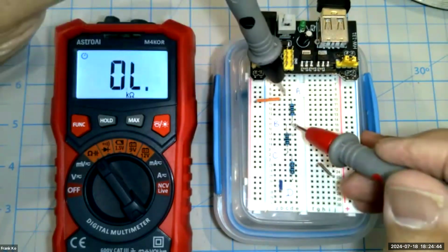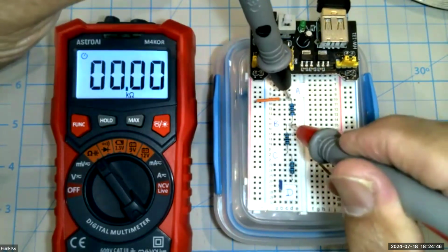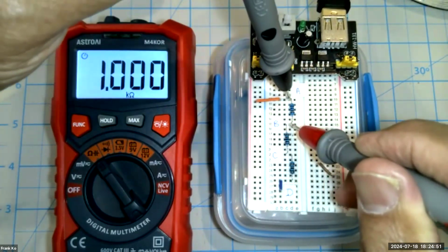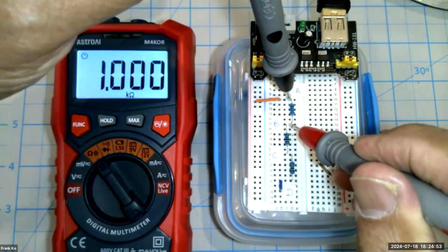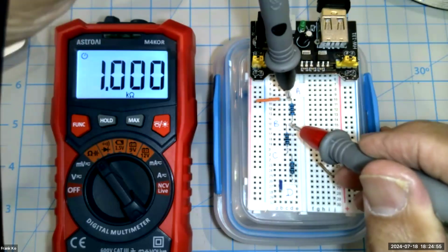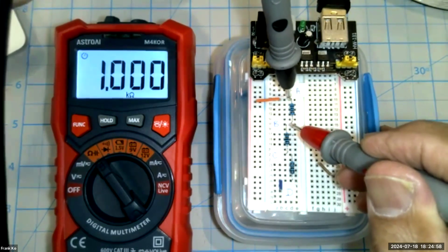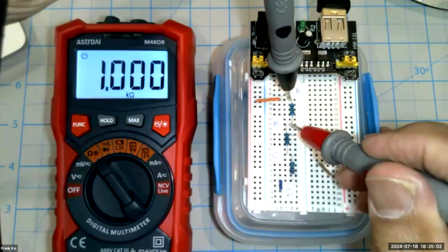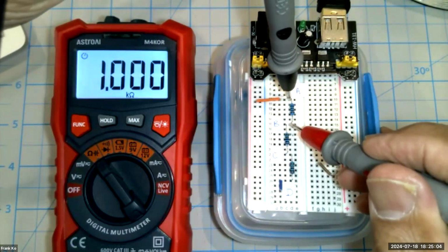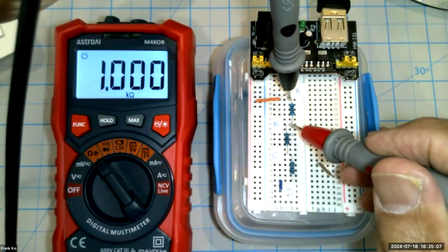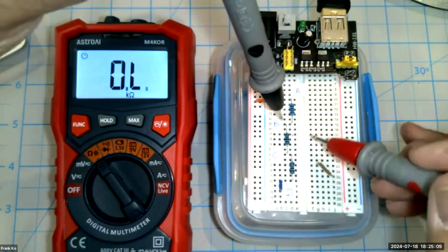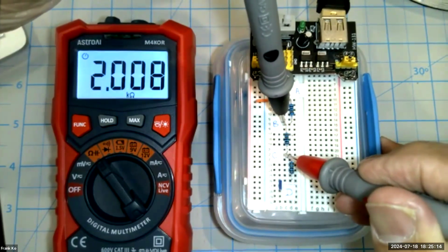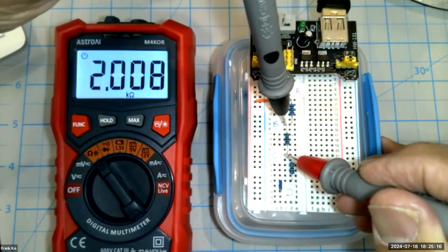So whatever you measure at this moment, along with me, you pause this as you need, you make the measurement, you need to record your values into your journal. And the thing about measurements is you record everything that's on the display. You don't round anything on the display. Unlike your calculator, where you're rounding to the hundredth, with a measurement, you record the actual value. That's just good lab technique. And then here, we would record an actual 2.008 kilo ohms.